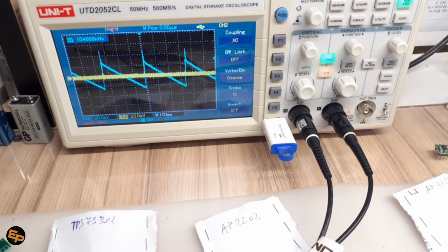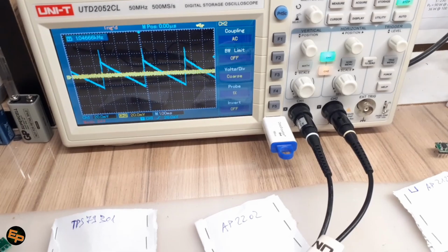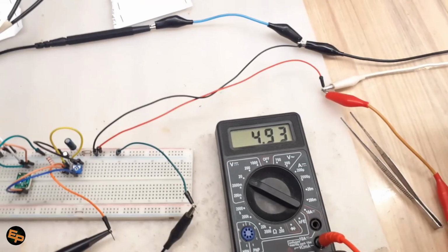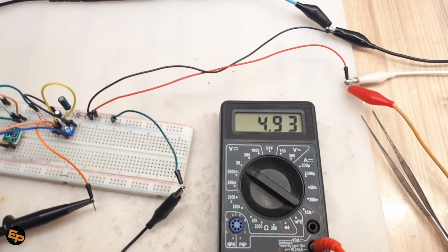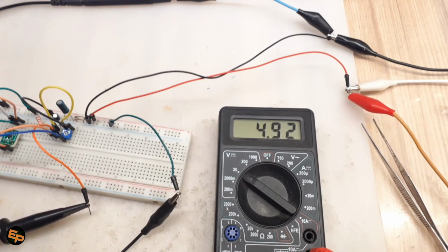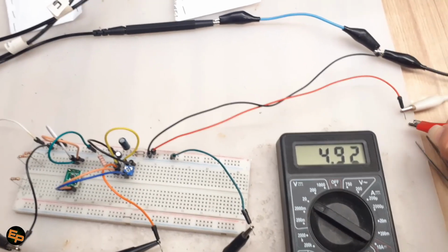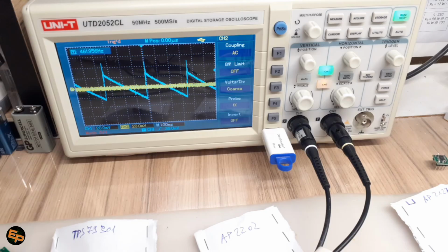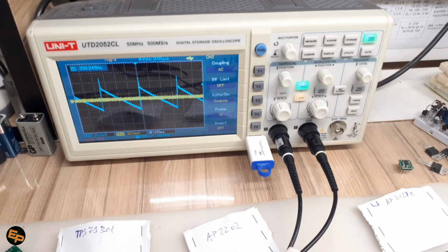Because a typical microcontroller board, at least one that does not have Wi-Fi or Bluetooth enabled, consumes roughly between 20 and 50 milliamps. So I decided to test the dropout of every regulator basically at 50 milliamps. And then I decided to test a higher current, and this depended on every chip, because every chip can output different amounts of current.